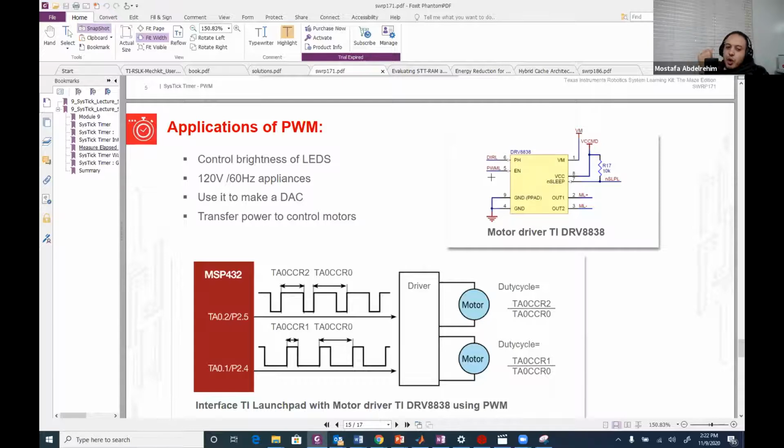And here, last time we put just 1, and I said it's full speed. So basically, if you don't feed it with 1 all the time, but feed it with a square wave with a changing duty cycle, you can change the speed of the motor. So we're going to use this pin, but this time we're going to feed it with a variable duty cycle signal, so we can change the speed. If we put just 1, the motor will move all the time at full speed. Okay, so let's see what we're going to do.